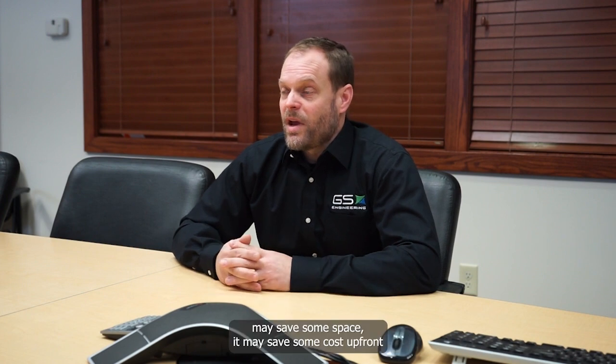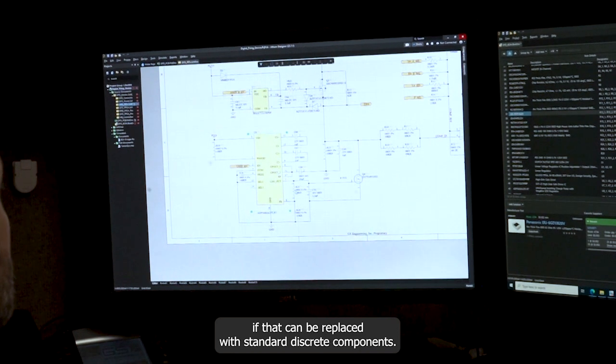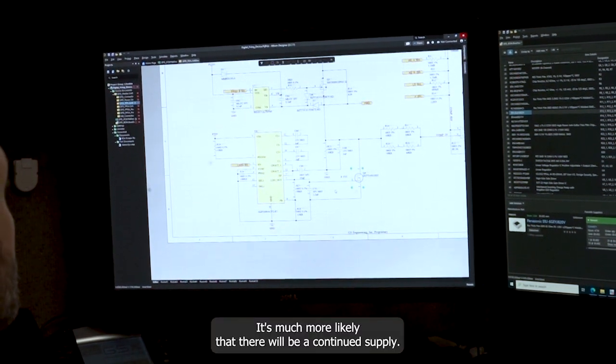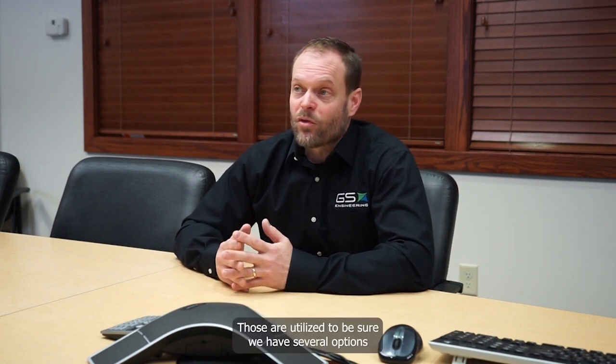So how do we avoid getting back in the same position in the future? Well, the key is to make the design more flexible and universal. So while a specialized integrated circuit may save some space, it may save some cost up front, if that can be replaced with standard discrete components, it's much more likely that there'll be a continued supply of them. Also, many of these devices are available in multiple packages, and wherever we can find a package that is common between multiple manufacturers and multiple parts, those are utilized to be sure we have several options when it comes time to filling the boards in the future.